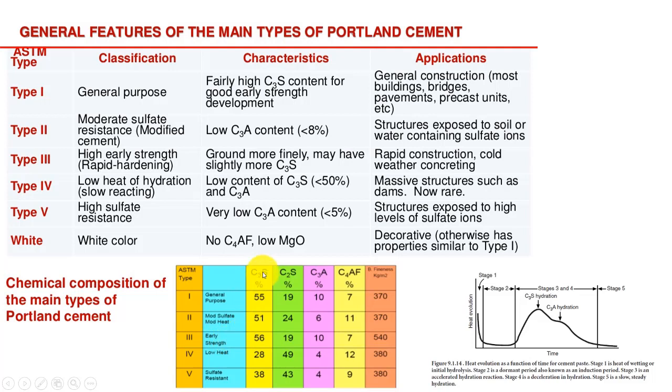You have a higher concentration of tricalcium silicate, and you can gain the early hardening, early strength by grinding this material, so that it can have higher hydration of the cement particles. I talked earlier about how cement only hydrates up to 20%. If you decrease the particle size, it would have a higher strength.